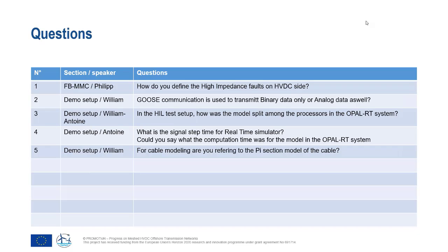Our analysis showed that it's really beneficial to have an active fault current control also to treat high impedance faults. But overall, these can be treated and overcome with a protection strategy. I hope that answers the question. If that was not exactly what you meant, please write me an email after the session and I will come back to you. Thanks.